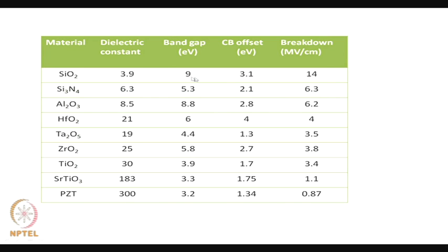Band gap and conduction band offset have also been tabulated, along with the breakdown field in megavolt per centimeter. For SiO2 it is the highest and for PZT it is the lowest. So, almost an inverse relation is obtained between the dielectric constant and breakdown.